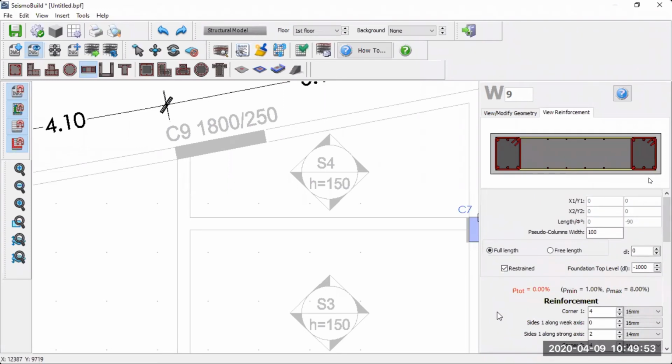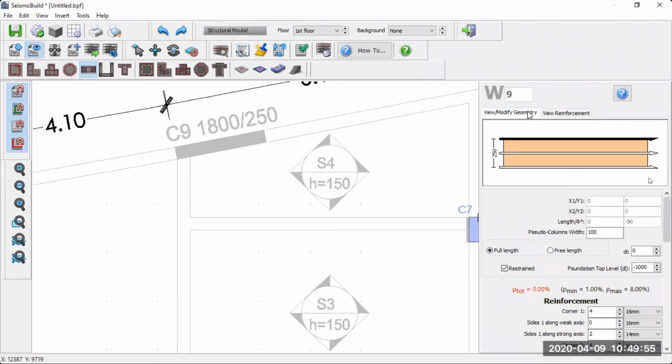So now we're going to show you how to insert the wall. If you look into this wall here, you notice that there are 3 parallel lines. These parallel lines indicate the line along which you insert the walls. In this particular wall, you can insert at the middle line, but in this example, it will be easier if we start from the corner.